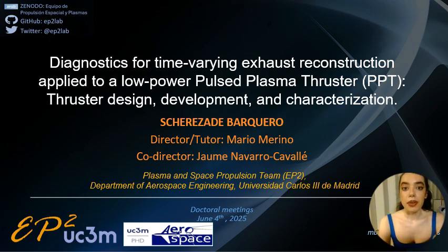The thesis involved the design, development, and experimental characterization of the thruster, in particular a PPT, as I've introduced, but also the design and applied results of innovative experimental diagnostic techniques for the time-varying 3D reconstruction of the plasma exhaust of unsteady electric propulsion systems based on electrostatic probes working in the ion saturation regime.